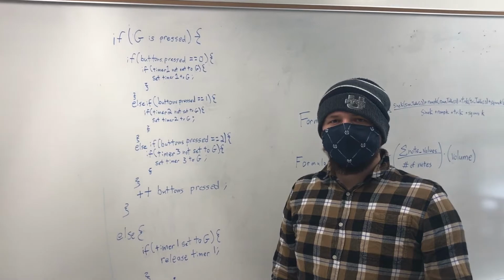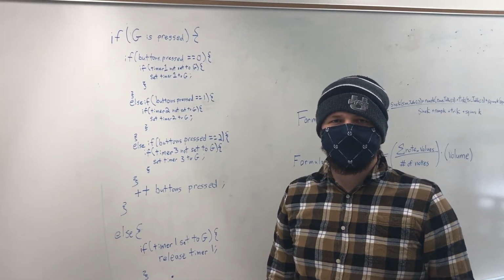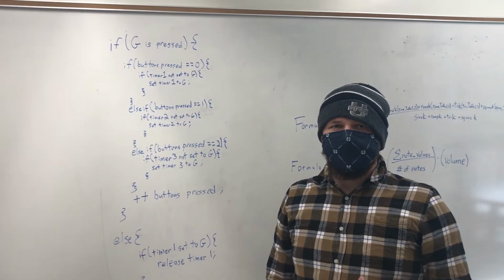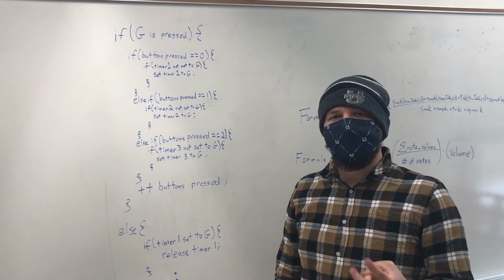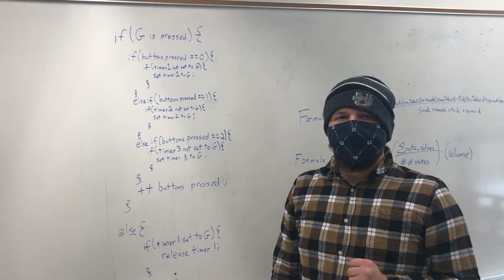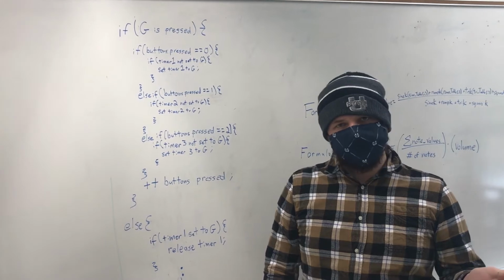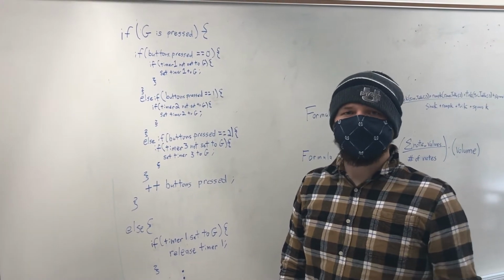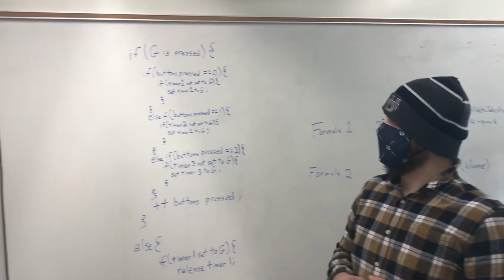And now I'll explain how the microcontroller generates the note values. To generate the note values, the microcontroller has 3 timers. Timers 1, 2, and 3. And in the main function of the microcontroller, it scans through all of the notes, starting with note C and working its way up. And when it scans a note, it follows this algorithm.